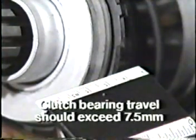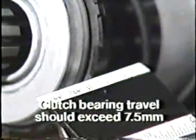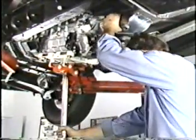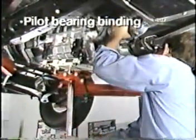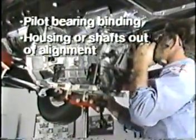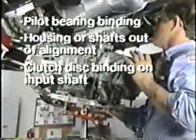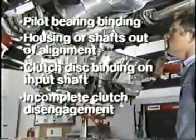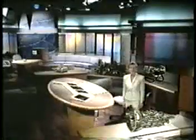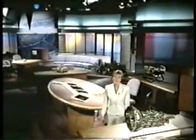If the suspected cause is clutch-related, check release bearing travel. If the bearing travel is less than 7.5 millimeters, the hydraulic system may be leaking. If the clutch travel seems fine, consider other possible clutch problems, such as pilot bearing binding, housings or shafts out of alignment, clutch disc binding on input shaft splines, and any other factor contributing to incomplete clutch disengagement. We've covered noise and shift concern diagnosis. Now let's move on to repair.